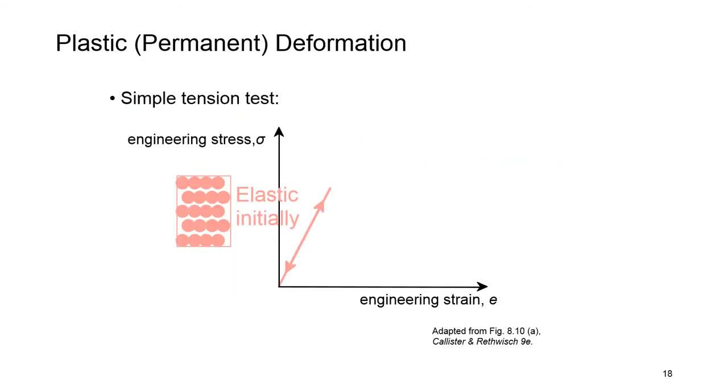As I previously stated, many of stress-strain behavior curves can be found using simple tension test. In this material, when we apply axial load, we see stretch in the bonds, so we will see increase in the length, increase in the value of stress, linearly with the value of strain for metals specifically. By continuing load, it starts to deform plastically. We already talked about plastic deformation, but here we have elastic plus plastic at larger stresses.